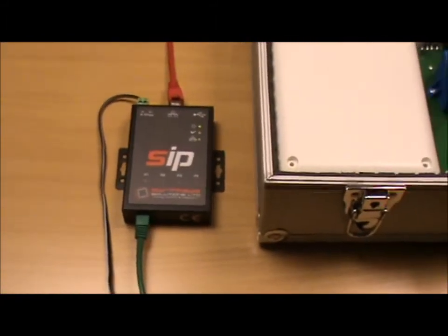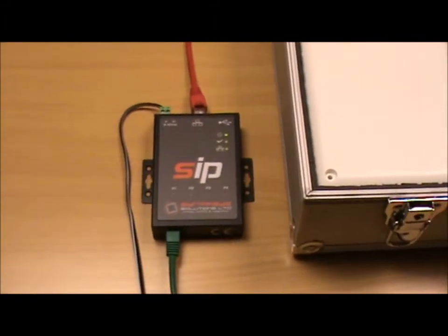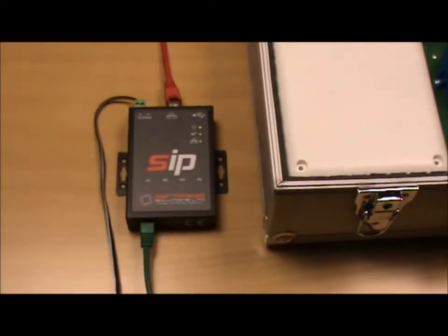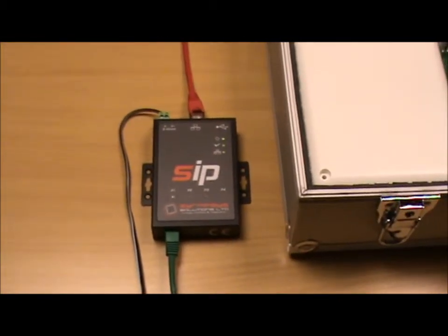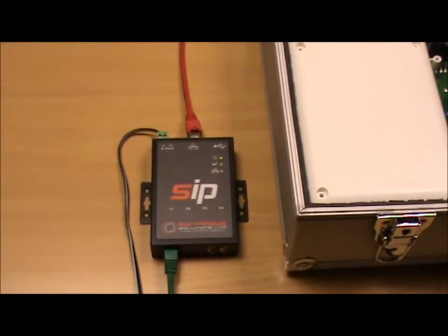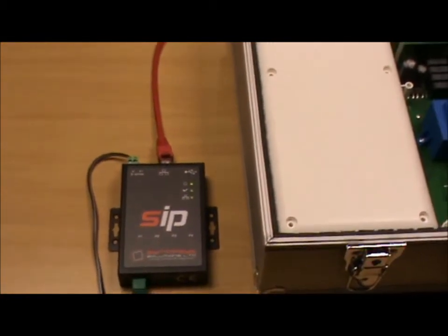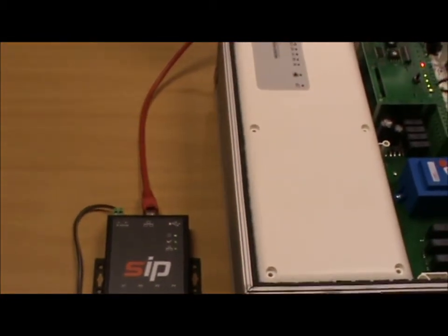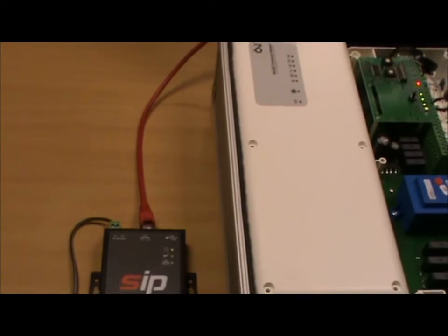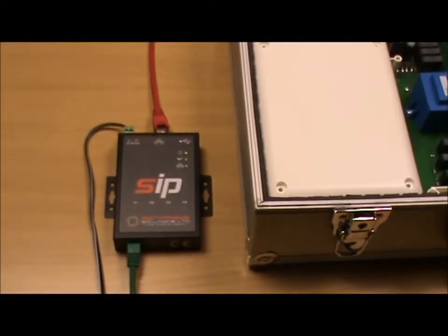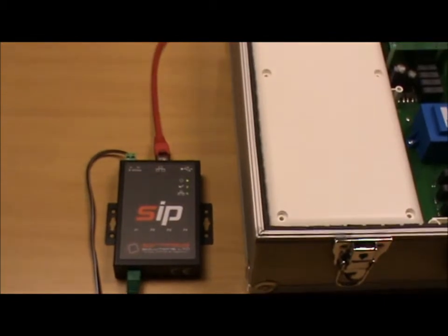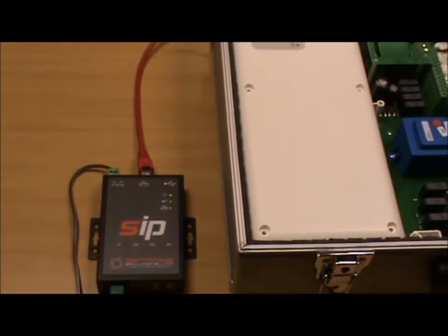In order to ensure that the two systems work together seamlessly, as the demonstration you've seen here, this SIP module and the BMS system subnet masks need to be the same, and the IP addresses need to be in the correct range. This will obviously vary depending on the IP addresses on site, and will be engineered on a site-by-site basis.